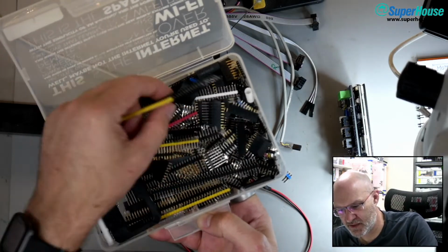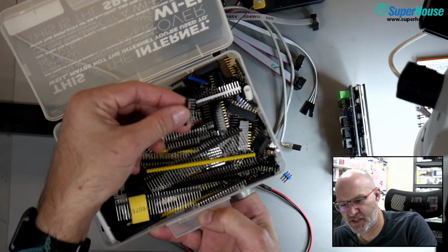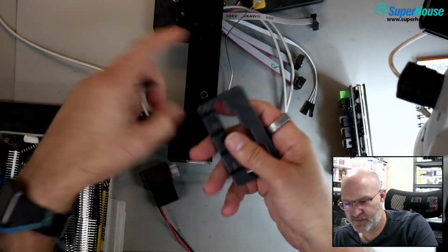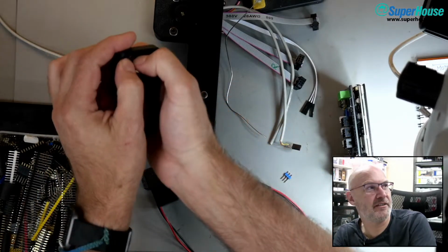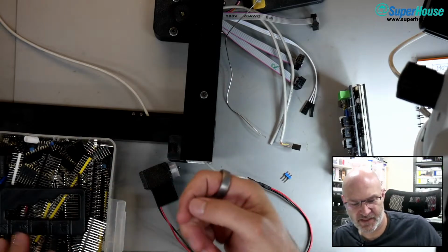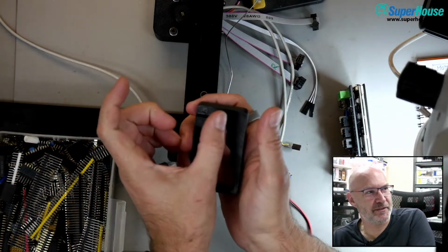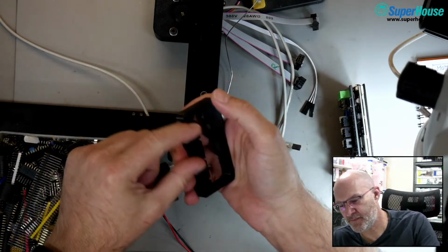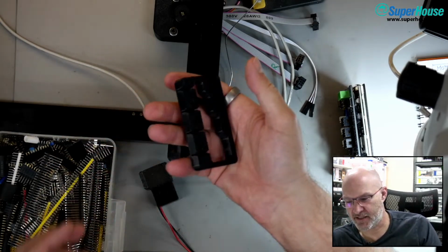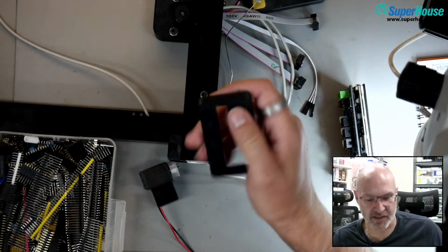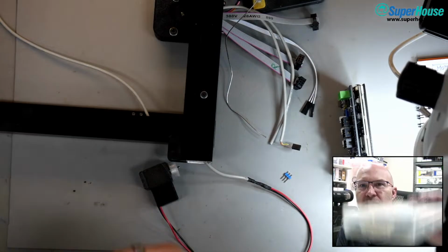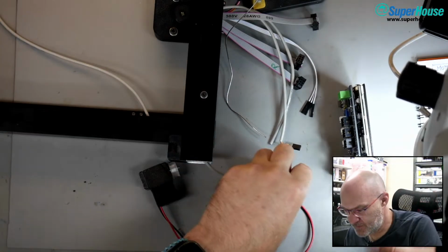where's an example? Oh, there's a pin header. So with this, I can just chuck this in, go snap, and now I've got 4. And it makes it really quick and easy because you get the 40-way pin header, you feed it in, and you just go snap, push, snap, push, snap, push, and you can go click, click, click, click, click, and just keep snapping off pin headers at the length that you want. And very quickly do dozens of them, which is very handy.